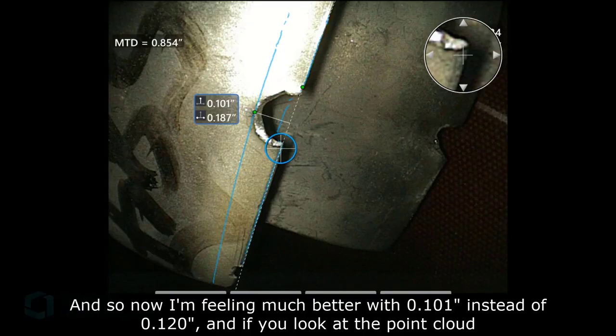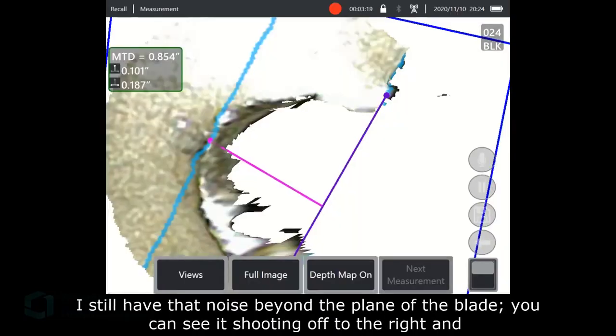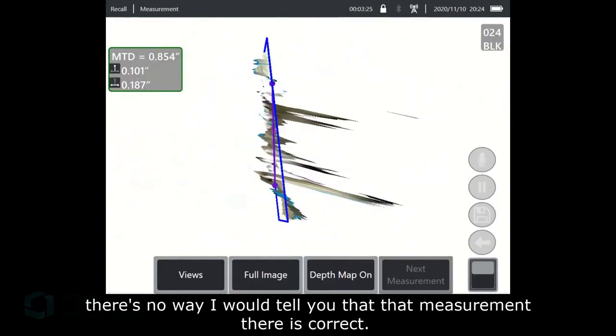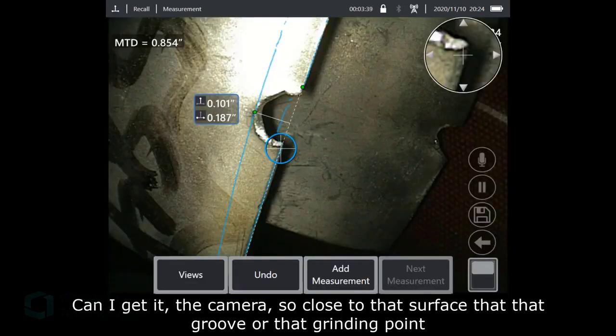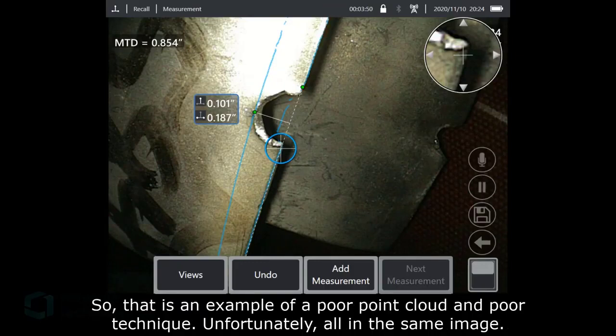And if you look at the point cloud, this did nothing to improve the point cloud quality. I still have that noise beyond the plane of the blade. You can see it shooting off to the right. And there's no way I would tell you that that measurement there is correct. I would say, can I get any closer? Can I get more magnification? Can I get the camera so close to that surface that that groove or that grinding point is filling up half or more of the screen to get a lower MTD? So that's an example of a poor point cloud and poor technique, unfortunately, all in the same image.